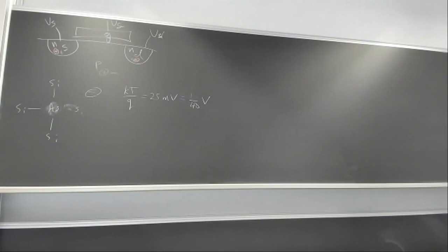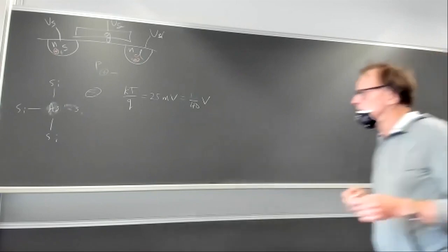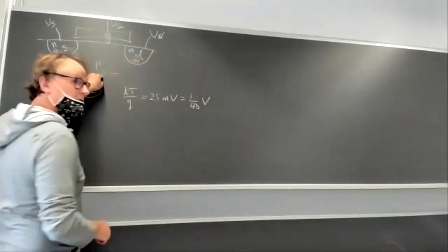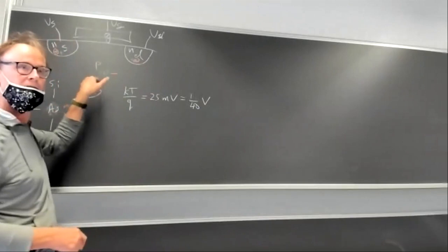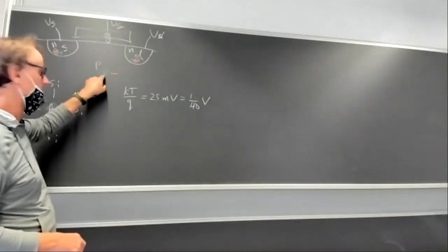And if you treat it quantum mechanically, it acts just like an electron, although it has a higher effective mass, so it gets accelerated more slowly by an electric field, like 2 times slower than an electron. But it's just a bubble. It's not a physical particle, but it acts like it in terms of the semiconductor. And the p-doped one has fixed negative charges and free positive charges. Yeah, free holes. There are holes whizzing around here. A hole's a positive charge.